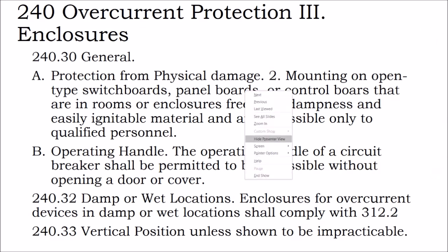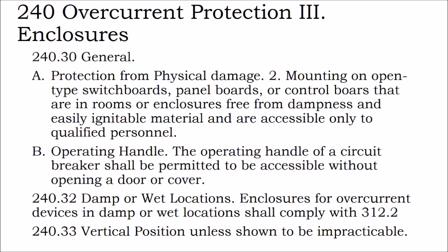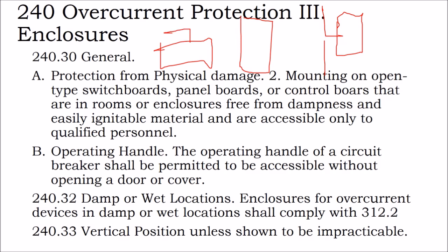And what that is talking about is that the switch needs to go up and down. So you have a knife switch disconnect, and here's your box, and here's the knife switch, and that needs to be in an up or down location rather than putting it on its side and having the switch be kind of in a left or right location. Now, what does that mean for a breaker switch? Our breaker switches on our loads are side to side, but then we have our main breaker switch that's supposed to be up and down.